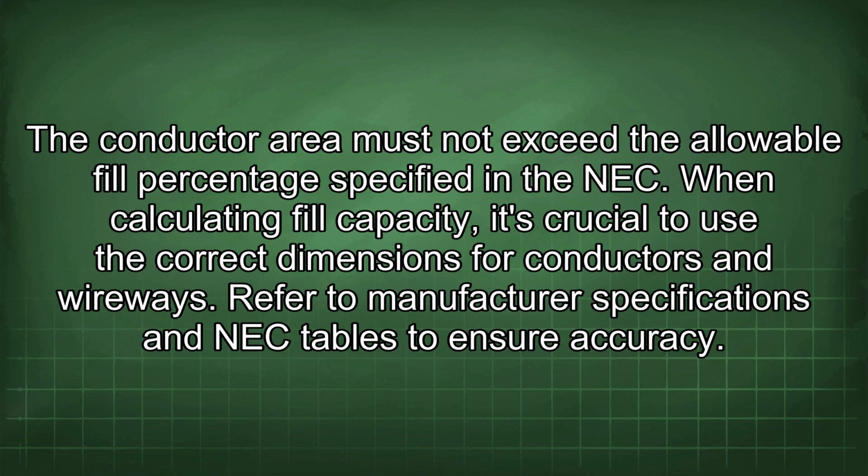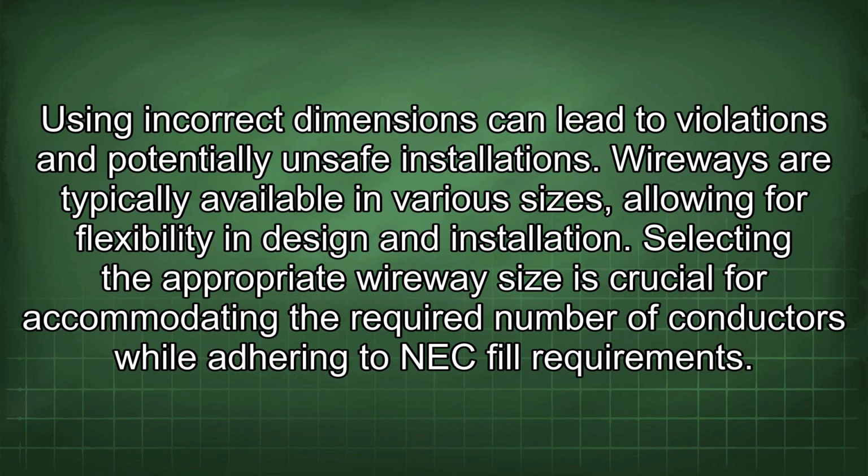When calculating fill capacity, it's crucial to use the correct dimensions for conductors and wireways. Refer to manufacturer specifications and NEC tables to ensure accuracy. Using incorrect dimensions can lead to violations and potentially unsafe installations. Wireways are typically available in various sizes, allowing for flexibility in design and installation. Selecting the appropriate wireway size is crucial for accommodating the required number of conductors while adhering to NEC fill requirements.